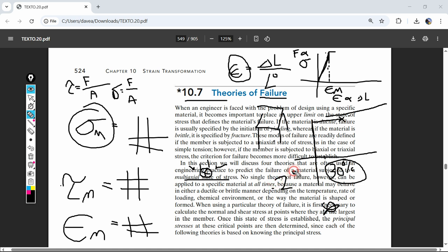So it is very ductile, even steel, 5 to 30%, but usually 10%, 5 at minimum typically, and 30 at maximum. And then we're talking 0.2% for the linear range. Just as 30% is proportional, this number 30 is a percent, so it's going to be 0.3. Whatever the length was, multiplied by 0.3, that's your change in length. Where this linear zone is 0.2, as a fraction you're going to have 0.002. This is steel's max strain.